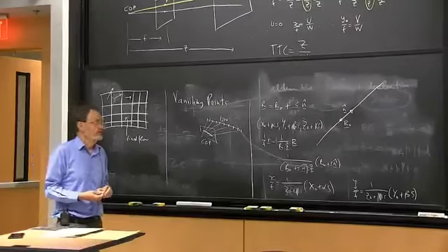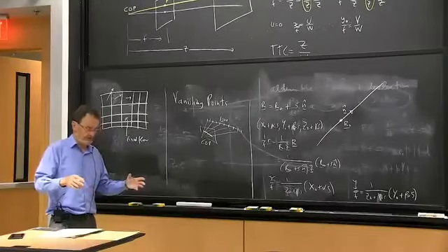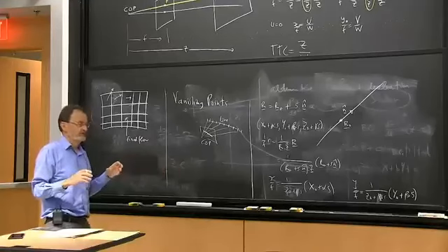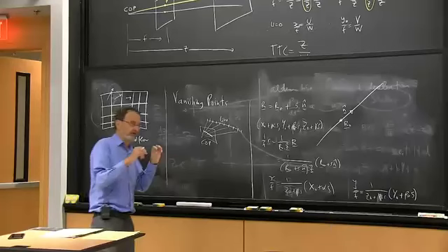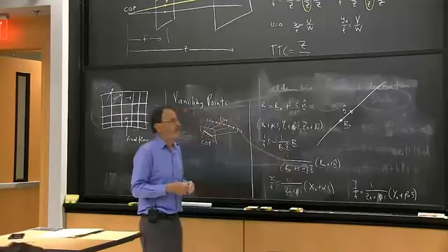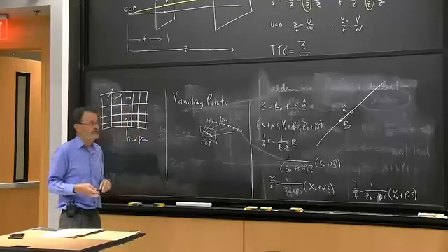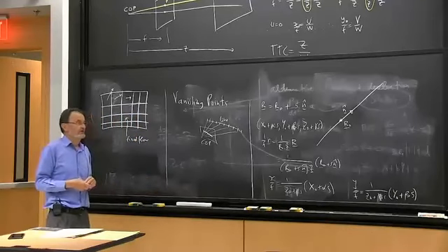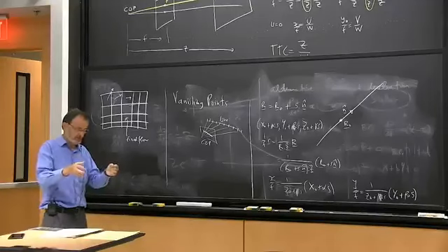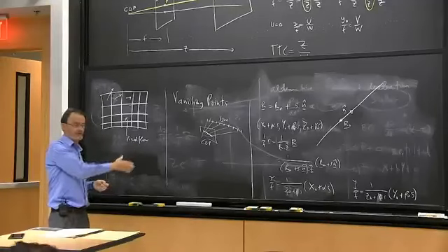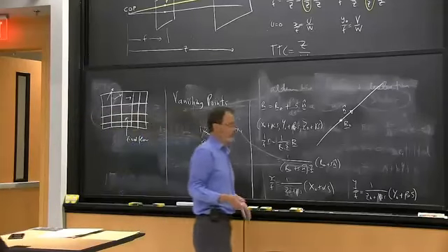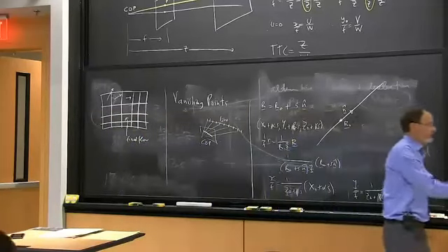But one of the things it needs to do is to figure out the geometry of its coordinate system and the road's coordinate system, right? Now, you don't want the person who's using it to have to come out with surveying equipment and measure the angles and so on. So the camera has to, on its own, try and determine the rotation of its camera-centric coordinate system relative to the road, x, y, and z. And so one way to do that is to look for vanishing points.